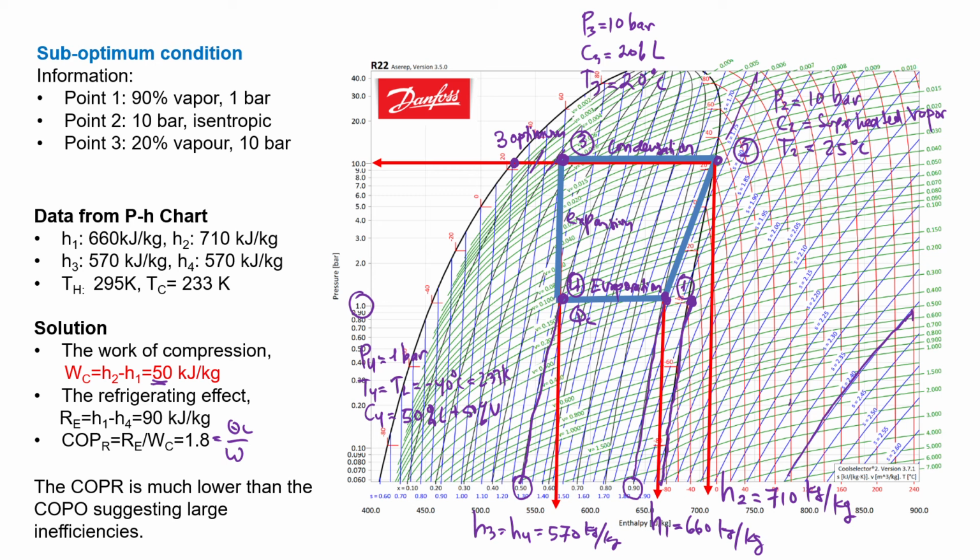That is all, so I can make a summary. The key concept to understand the refrigeration cycle is, first, we understand how to use the pressure enthalpy table. We know the condition of the fluid when it is subcooled, when it's saturated liquid, mixture in between liquid and vapor. We have also the condition at saturated vapor, then superheated vapor.